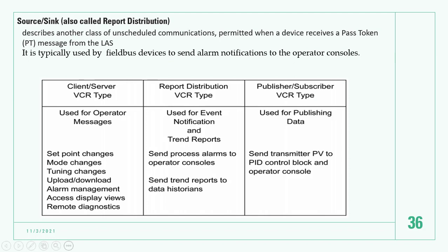Source synchronization is called report distribution. It describes another class of unscheduled communication, permitted when a device receives a pass token message from the LAS. Source synchronization is mostly used to send alarm notifications to the operator console.